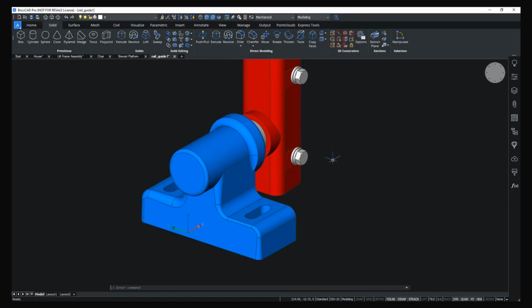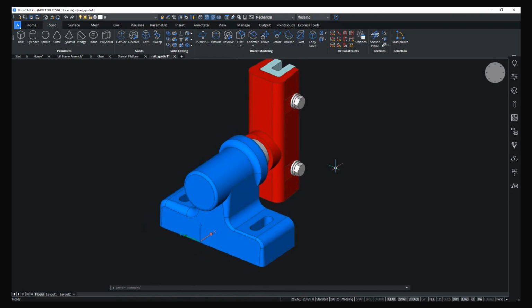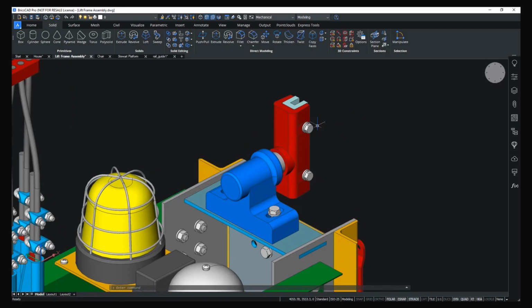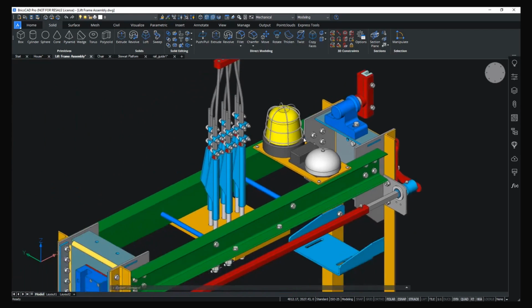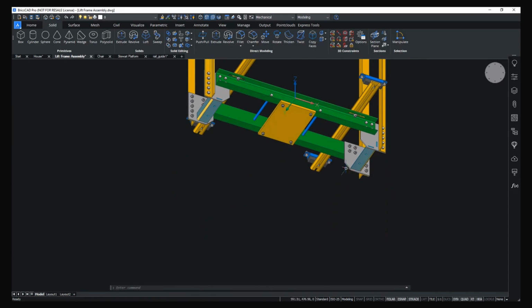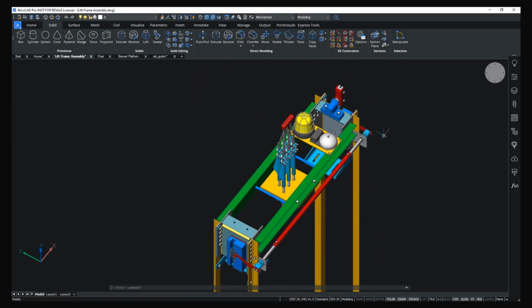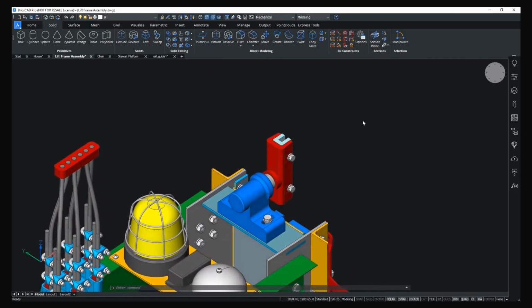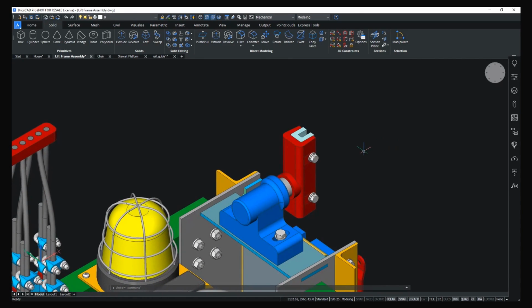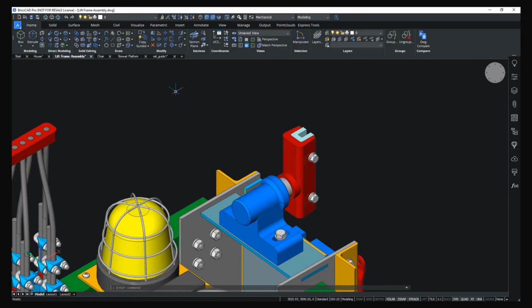During last week's webinar on BricsCAD Lite, some innovative design assistance tools were showcased, such as Blockify, Copy Guided, and Move Guided. You'll be happy to hear that most of these features also work in 3D. In this example, I want to copy this rail guide over to other locations in the drawing. So here on this side, and then also on the bottom on two sides. Now I could manually mirror and copy this part to their appropriate locations, but it's more fun and easier to let BricsCAD do the heavy lifting for me.